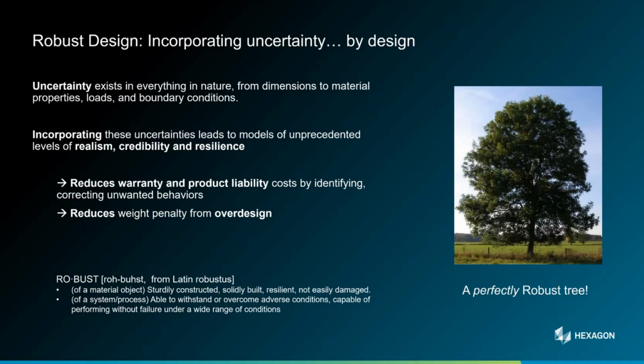examples. So why would you want to do robust design? Well, nature is varying. You have uncertainties and you have variabilities. Uncertainties: how can you know exactly what the density of the material is, or what the fatigue curve of the material is? It's just a certain scatter, a certain uncertainty. You cannot nail a descriptor with one single deterministic parameter, right? You know that there is a certain bracket. But some other things just vary by nature, like the loading, how the customer is using your products. You cannot put a number on that.